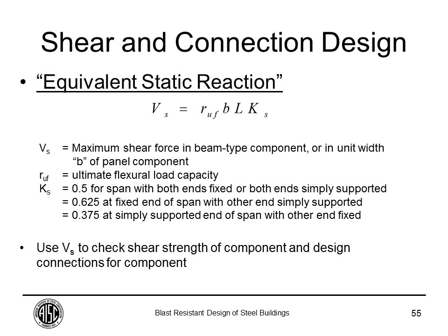So let's just talk about the shear and connection design, which is the very last step. We went through the whole process, and now we know how to check the flexural response against the response limits. We know when it works. We know when it doesn't work. The last step, which is probably the most important one, is to make sure that we ensure a ductile behavior. So to do that, we want to make sure that our component has adequate shear capacity and that the connections are strong enough to develop the full flexural capacity of the member.